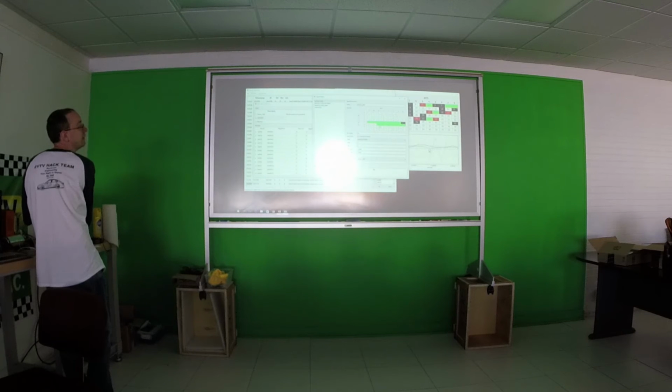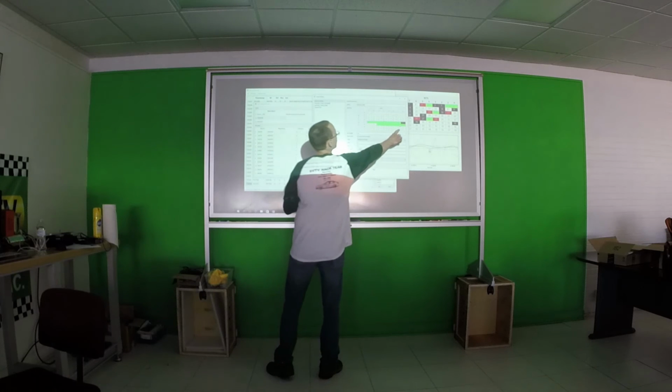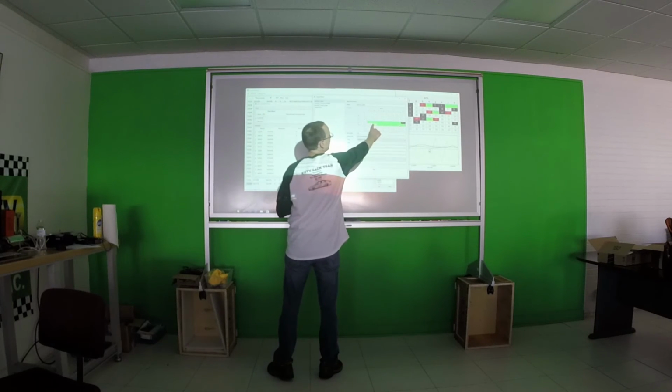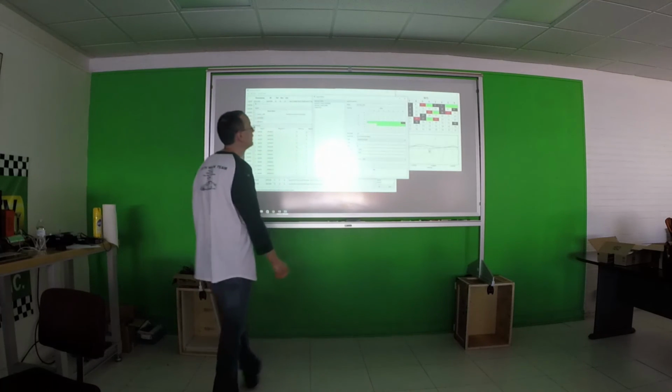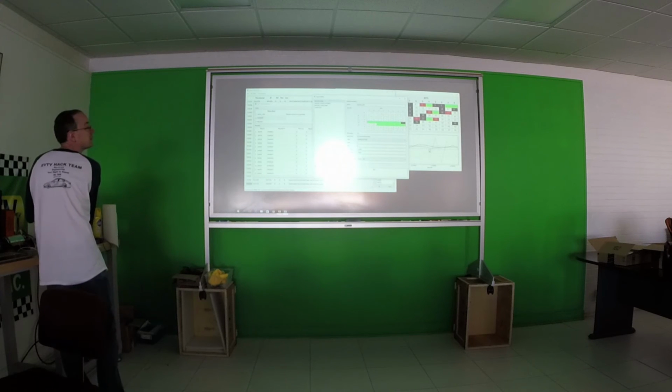Here's a 14-bit signed integer. And this shows how little endian works. We're starting here, going through here, coming back to here, and the 14-bit ends there, so we're not using bits 15 and 16, because that's just the way that Tesla works. The minimum value is negative 16,000. Max value is 16,000 for that on the RPM here. So the RPM is stored on a 1-to-1 scale. That's just one scale.